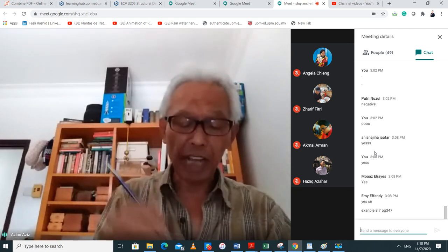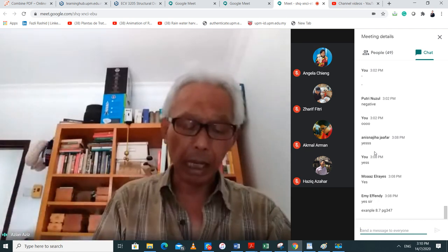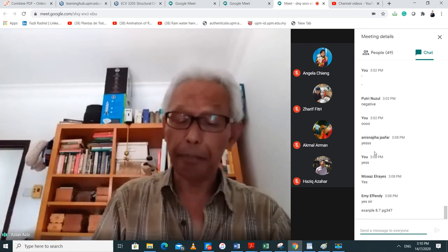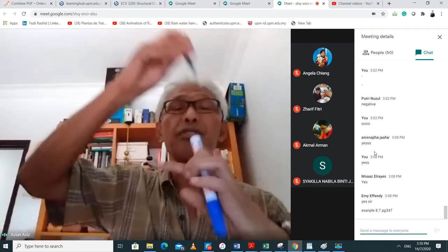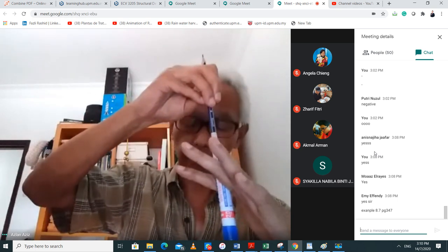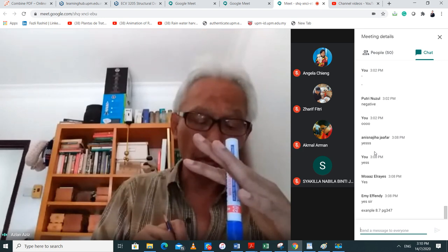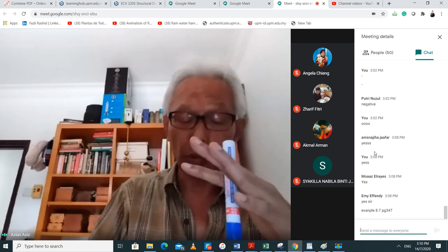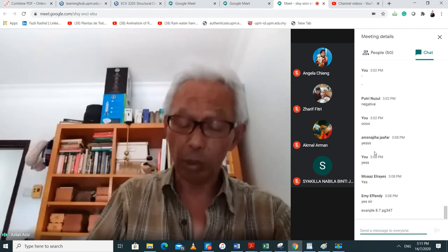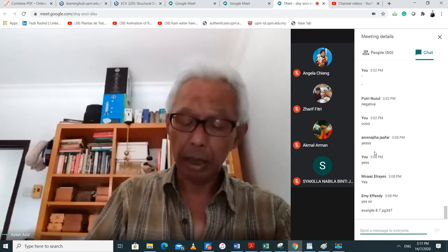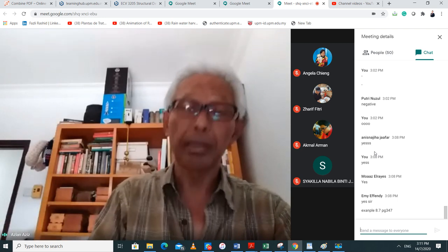So 1.5, 4, 3, 6, 4.5, 13, and so on. Now, the pile is required to support a compressive load of 650 kilonewton. So here's my pile, 650 from the top, compressive. And to withstand an uplift load of 225 kilonewton. The load factor in each case is to be at least 2.5. You need to determine the depth to which the pile must be driven.